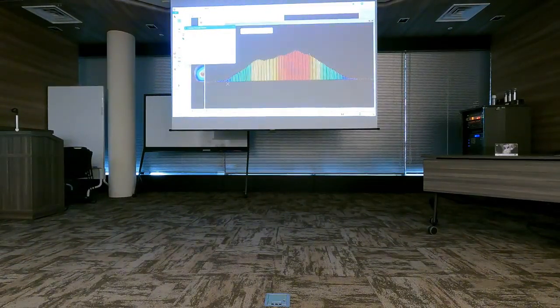I do want to see that the software has computed the whole stockpile, that I didn't accidentally place the bounding polygon somewhere here, and that would result in missing some of the stockpile volume. So I am checking that the base surface, which the software created on the fly, matches the stockpile. Here you can check whether the drawn polygon is properly covered, the ground level, and the height of the point cloud.